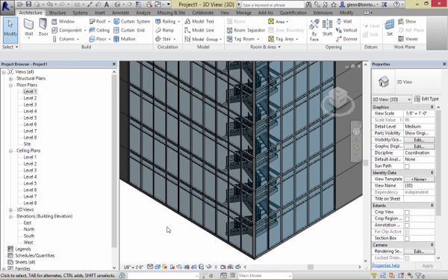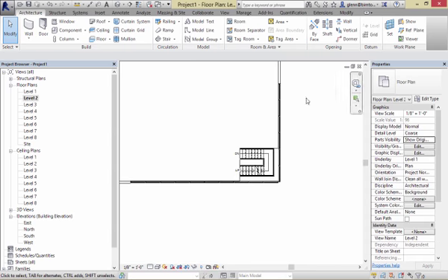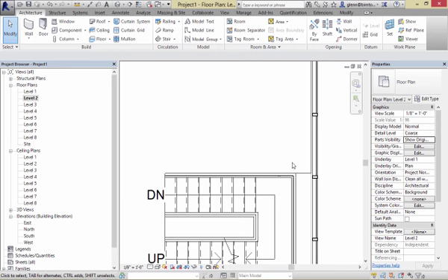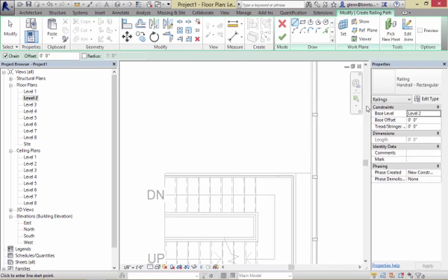Now the last thing you typically have to do on a multi-level stair like this, though, is you still have to go back and fix up the rails. We still have that problem where people coming in on the second floor are going to hit that rail and be in trouble, or hit that hole in the floor. So I'll go to level 2. And I still want to clean up this rail, so I'll put a rail in here. This one actually is right. I'll show you. It does kind of clean up the way you want.